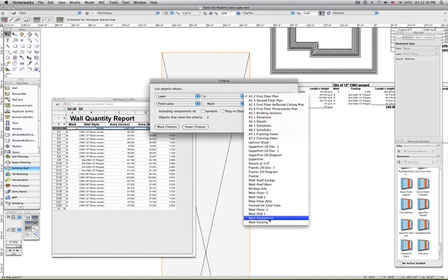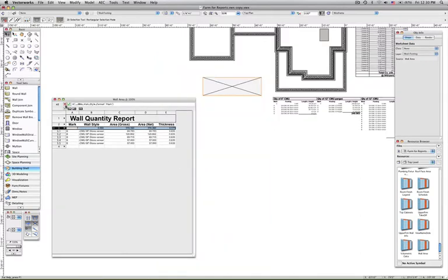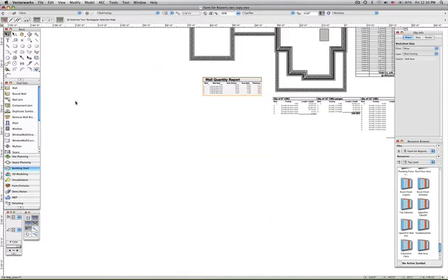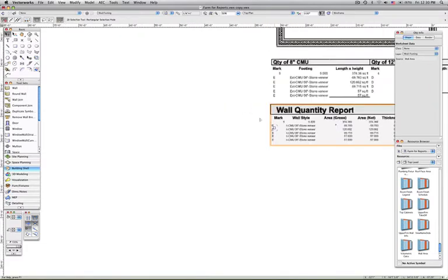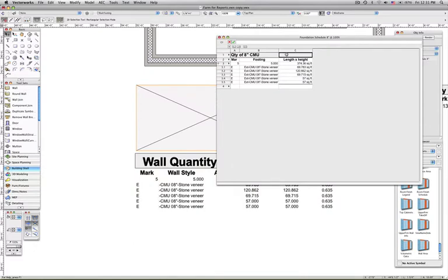And now, having done a little math behind the scenes, I know that one block equals approximately 0.89 square feet of surface area. We'll use this to write a formula that calculates the quantity of 8-inch block. And I'll enter that formula into my pre-formatted worksheet that will give us the number of 8-inch block on the job. Okay, hey, that looks good.